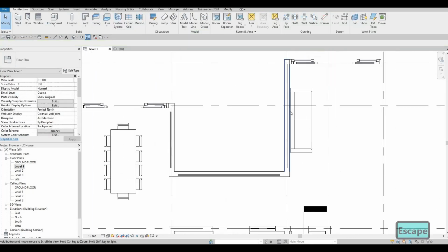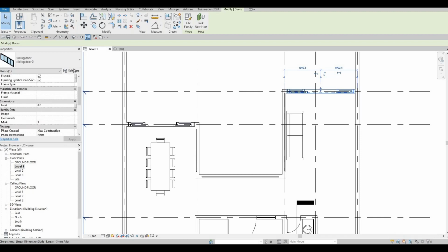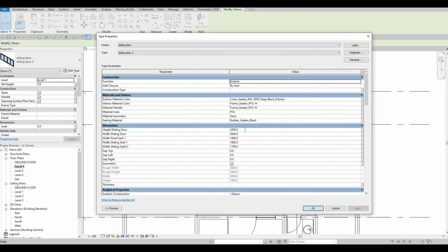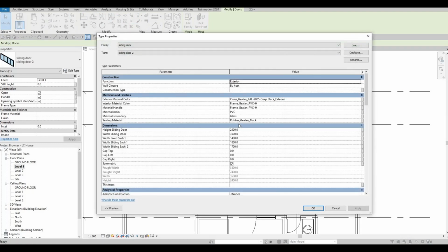And I think if we do a floor to ceiling right here, we need to edit the height of here. So why not just put this one at 2800 as well, so that everything looks similar in height. So it's just regenerating, and then this one 2800 as well.